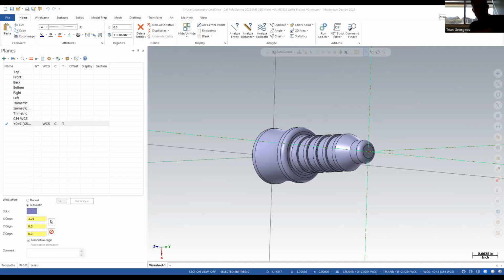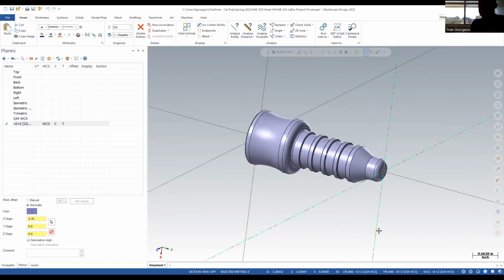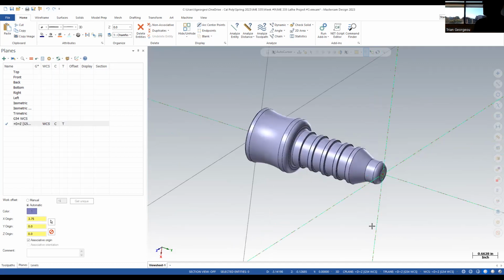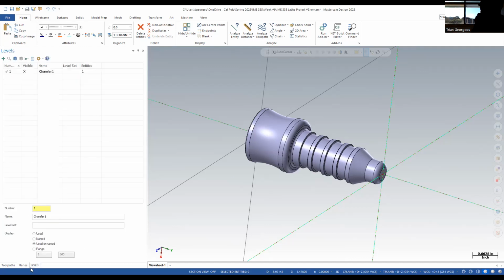So now we need geometry, don't we? I hate to break it to you, but all 2D lathe is programmed with 2D wireframe. Oh, geez. We can't use this solid model other than to create the wireframe. So what should we probably do with our levels if we're going to create some external geometry? Let's just create a wireframe level for wireframe programming. So we'll go over here, we'll call it 2, and we'll call this wireframe geometry. Just geo works for me.